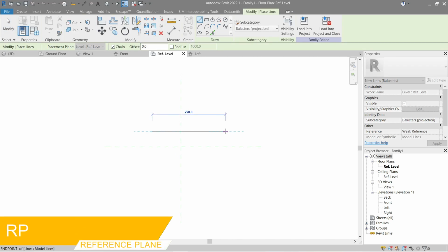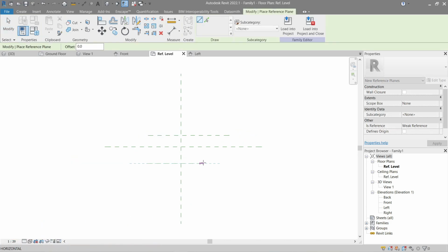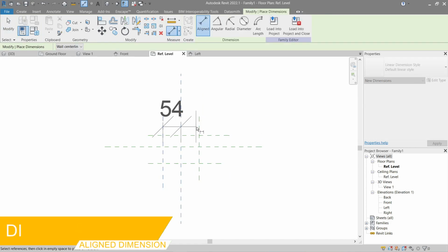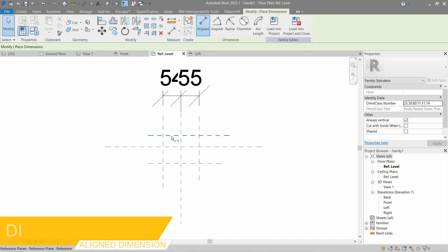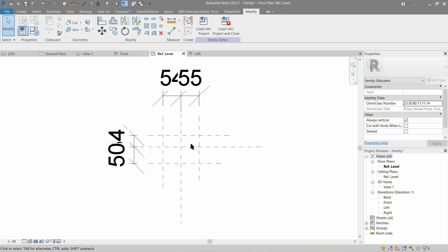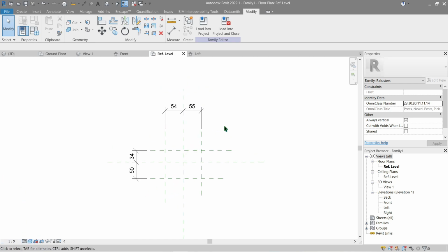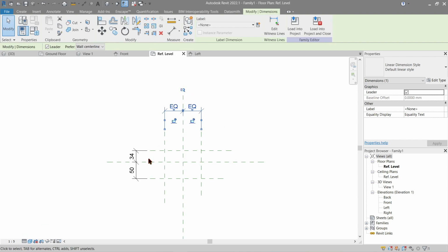Let's make a reference plane here first. I always like to make mine parametric. It's a good practice to keep doing that other than making just some simple extrusions. So here, our scale is too big. Let's make it 1:5. There. Now, let's equal this reference plane.